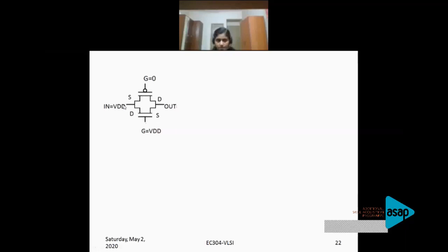Now when I have a logic 0 over here, this output capacitor discharges to 0, right? So once the voltage becomes lower than the threshold voltage, your PMOS will be switched off. Switched off means this offers a high resistance path, but in this case, depending upon the VGS and VDS equation, your NMOS will always be on if I give a 0 over here.